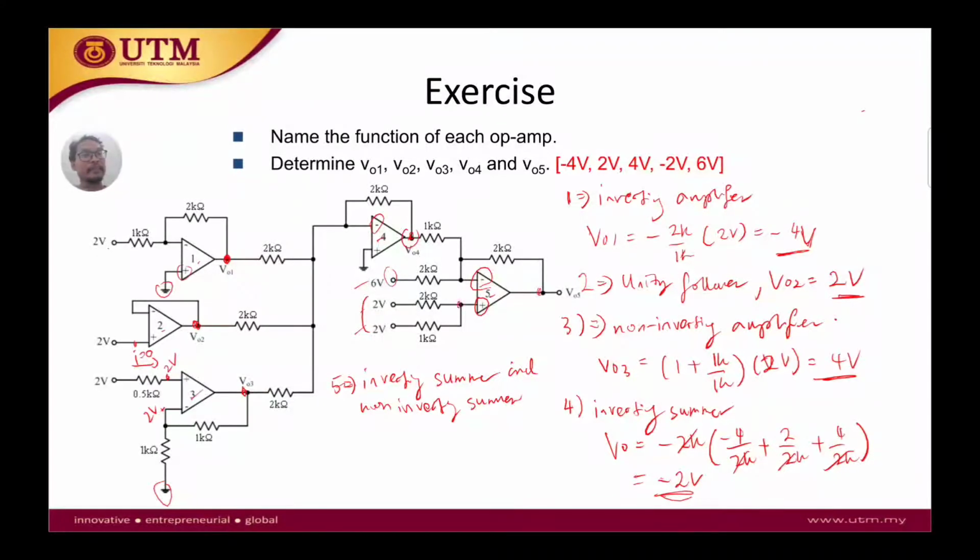The first step is to calculate your Vx here, where you probably have to derive yourself. If you do the derivation as shown in the previous slides, you are going to get Vx equal to 2 volts, which is just a combination of these 2 volts together. Now, if Vx is 2 volts here, then here is also 2 volts on this node on the V minus.